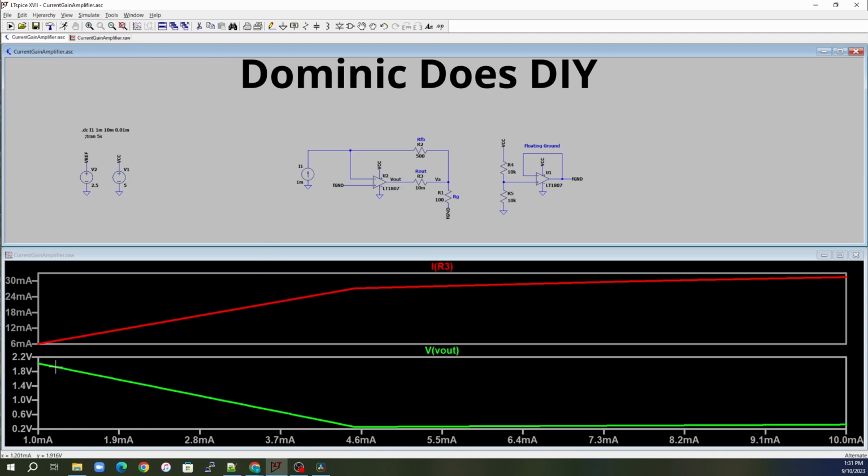And you can see our line gets extended all the way out to 4.517 milliamps before the output of the op amp becomes saturated on the low end. So now we can get out to beyond 4 milliamps as an input, which means we can get to 24 milliamps on the output, which is really good.